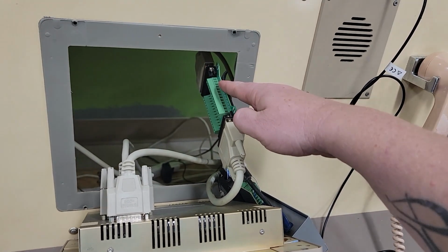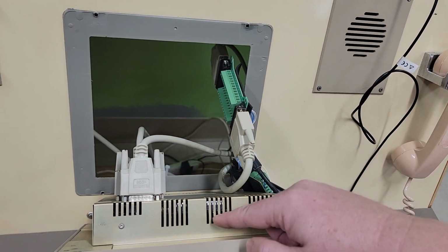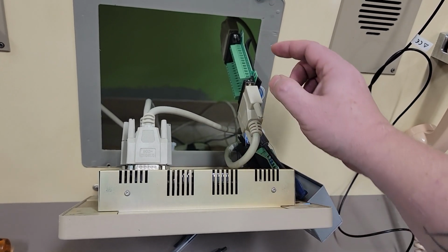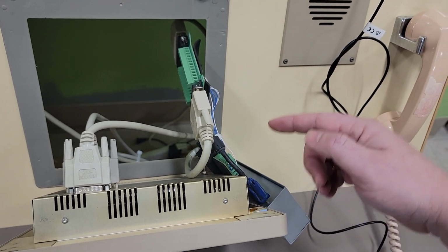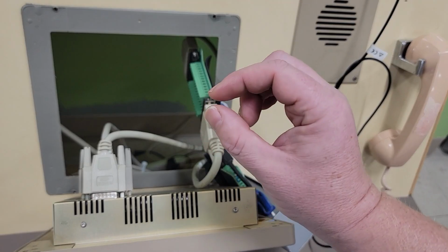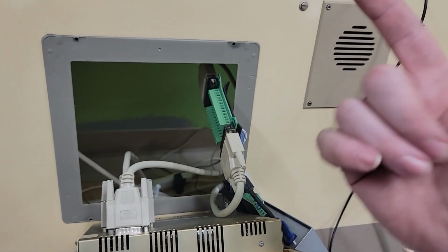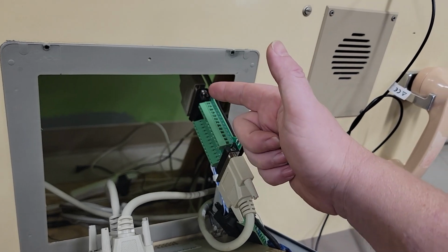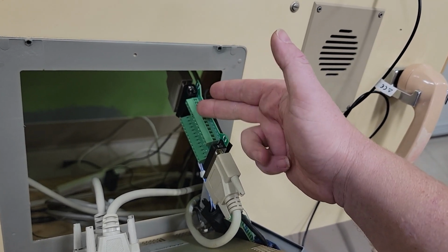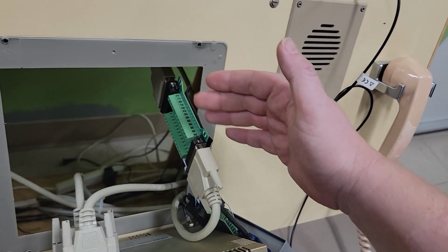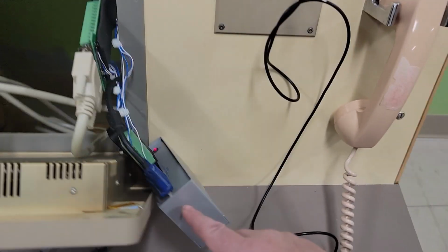So what I got to do is make sure that when the signal is fed through here and then it comes to the other side, this touch screen acts as a load, and if that load's there, then I can't also get it over to the display because the signal amplitudes decrease significantly. So what I have to do is tap off one of the red, one of the green, one of the blue, a horizontal and a vertical sync signal, and then pipe it to basically